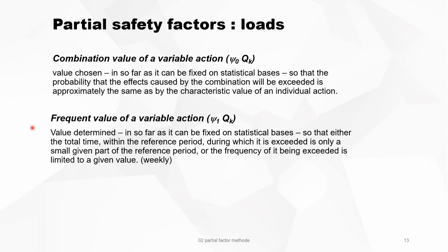The frequent value is a value determined insofar as it can be fixed on a statistical basis, so that either the total time within the reference period during which it is exceeded is only a small given part of the reference period, or the frequency of it being exceeded is limited to a given value. And we are talking here about a reference period of weekly. So that's the frequent value of a variable action.